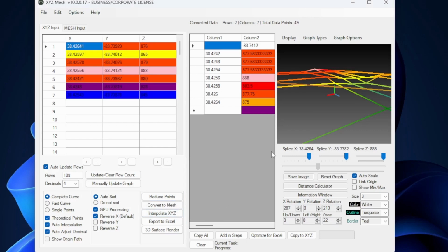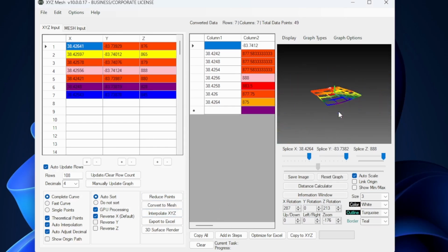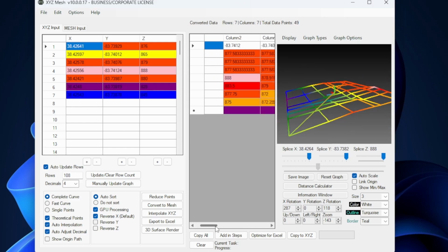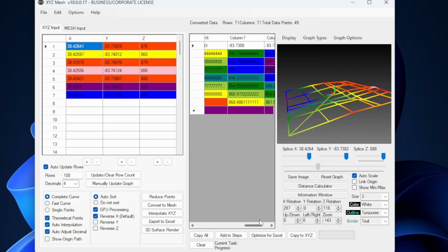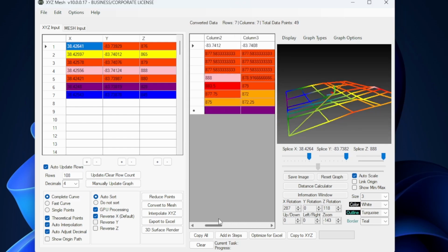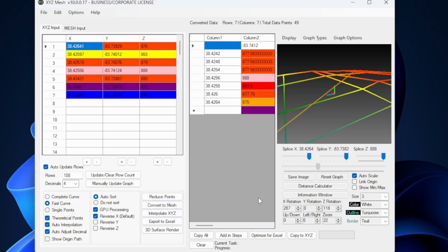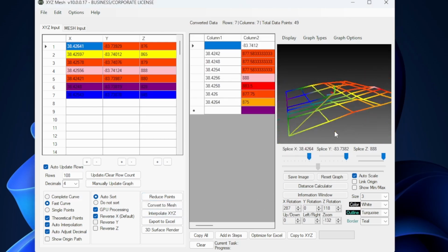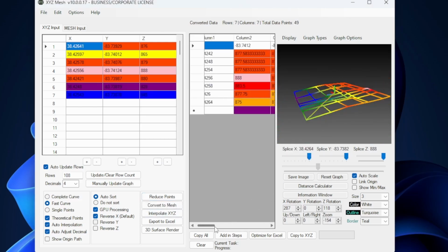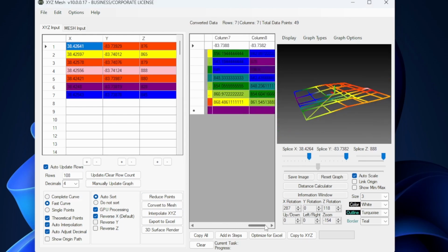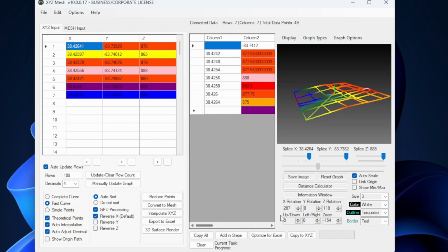This will loop continuously and perform hundreds of passes to make sure that all data points are filled in before the graph is completed. This option does take a bit longer to complete, but produces the best results. Second is called a fast curve. A fast curve sends the data through a minimal amount of passes needed to generate a complete enough graph version of your data. Sometimes this could be a completed curve, but many times corners may not be calculated while the center part of the graph is.